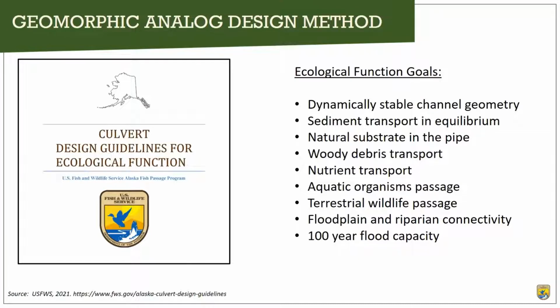This is definitely a concern: how much flood capacity do we need? Currently, state guidelines on state highways for culverts are for 50-year flood capacity. So this 100-year flood capacity is higher than what folks are typically using or have been using in the past. Should we be using a higher flood capacity? Maybe. Can we afford it? I guess that's the question for each project, is to look at your project and see if you can afford it. Certainly, the higher your flood capacity is, the better.